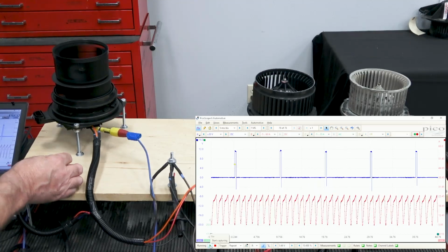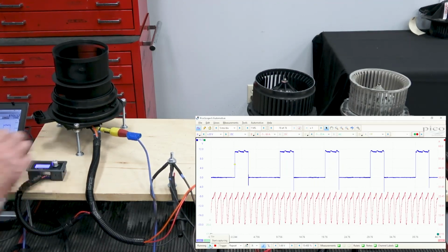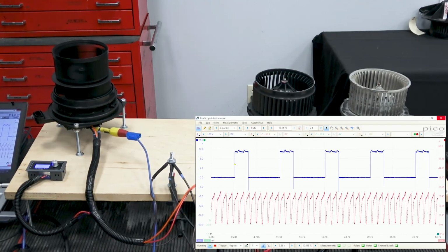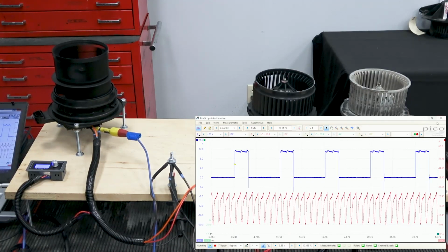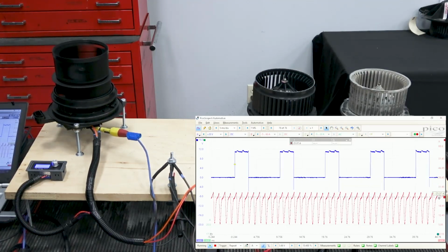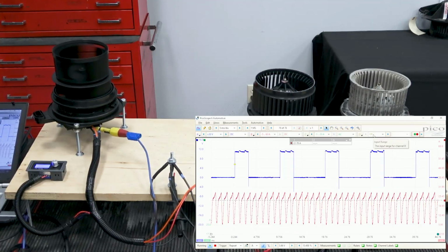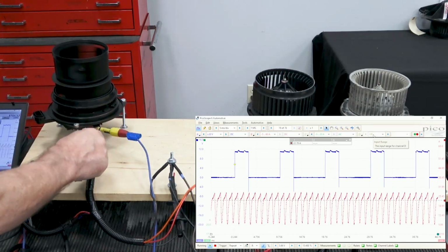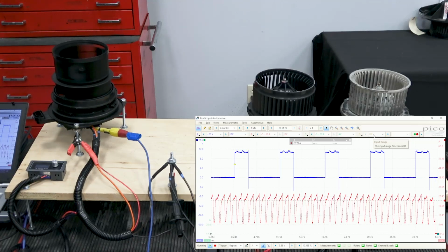And now I overshot a little bit. Let me just go back to 30%, which should be about full maximum speed. And you can see the duty cycle on top there, the pattern actually represents about 30%. And if I pull a red cursor down, on average we're probably about 22, 23 amps. So that's how we could use an oscilloscope to check a brushless blow motor.